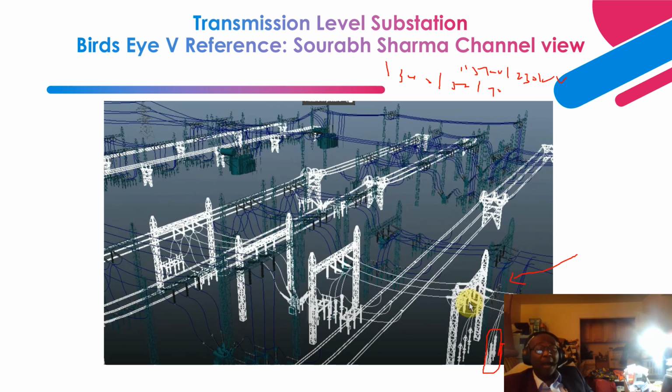That is part of your insulation coordination studies that are done during the planning stage of the project. Underneath this substation tower, this is connected in a shunt configuration. These are CCVTs, either VTs or CCVTs. VTs for high voltage substations are the inductive type of voltage transformer, and this is usually connected in a shunt configuration.